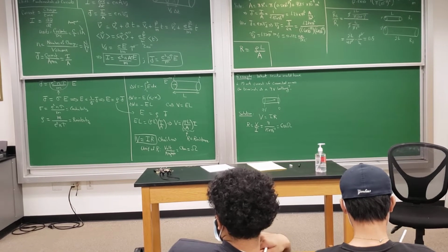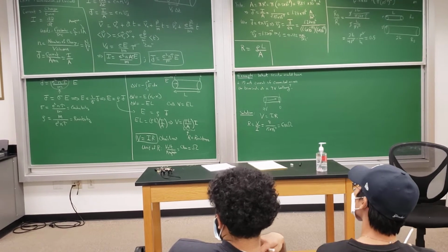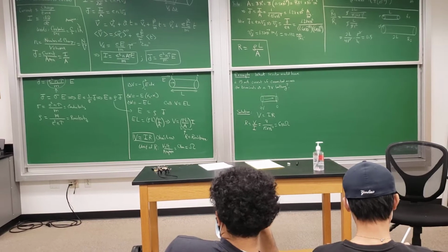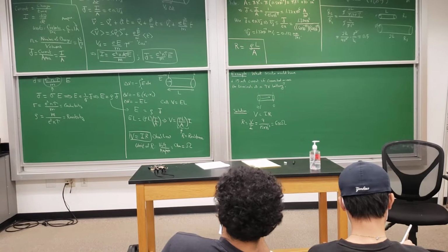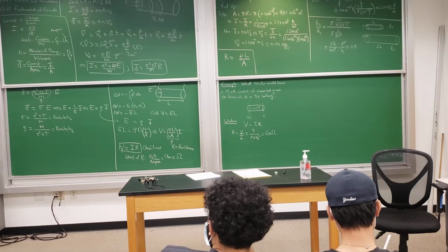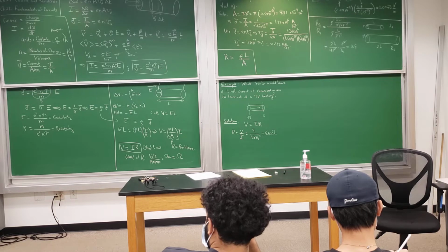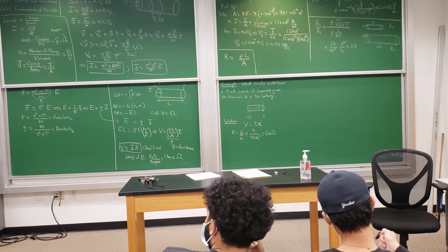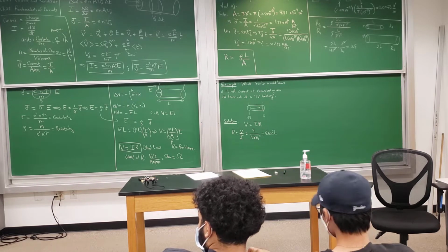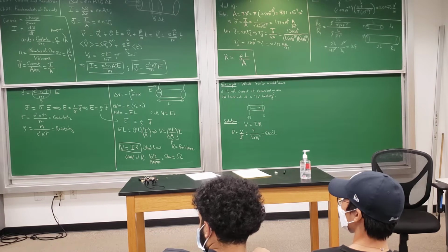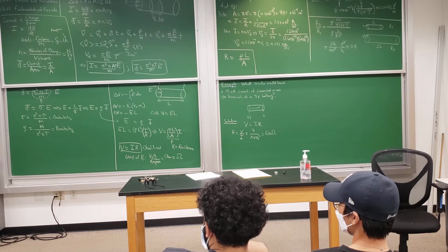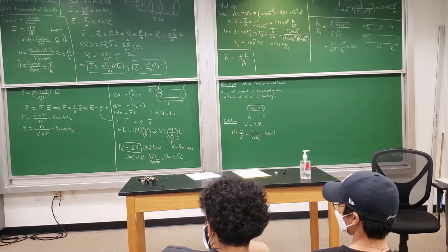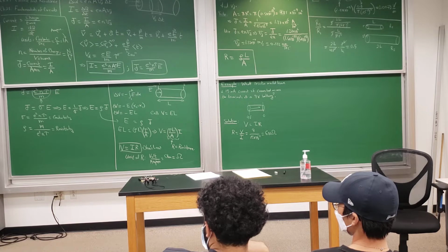They're called direct current, DC, circuits because the current does not change direction. If the current, let's say, flows clockwise in the circuit, it will continue flowing clockwise. If you only have resistors involved, the current will keep the same direction and same magnitude. It doesn't change. If there is a capacitor, it will keep the same direction, but there is a chance it might change magnitude. A lot of times when the capacitor is fully charged, it will oppose the current. Eventually the current dies off. It will go to zero.